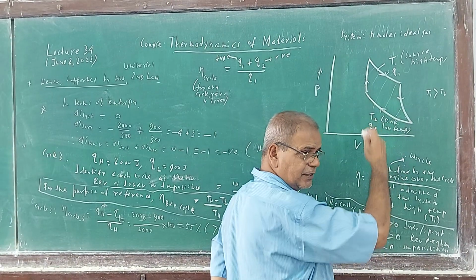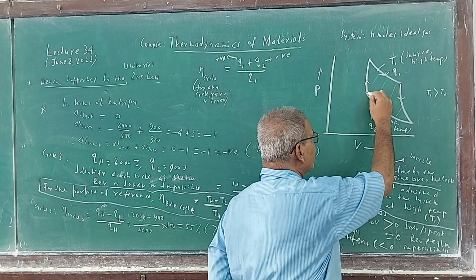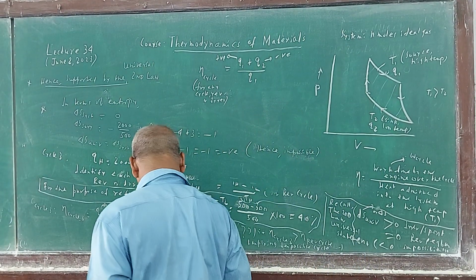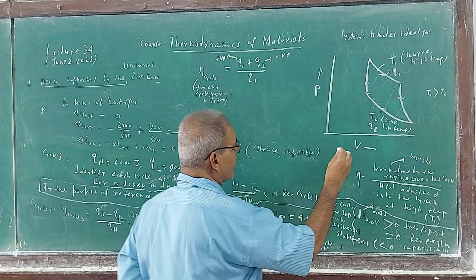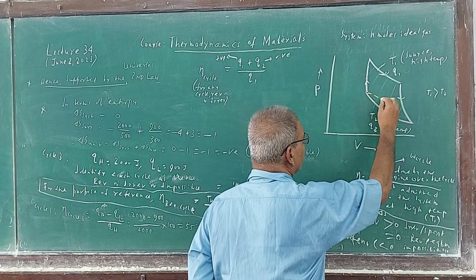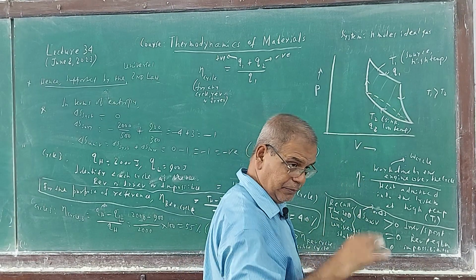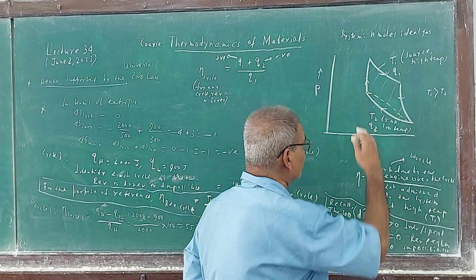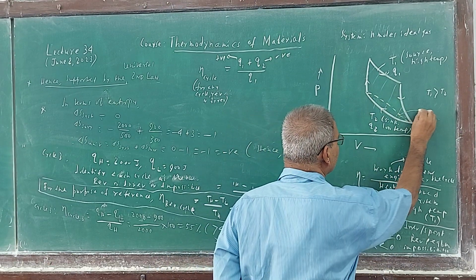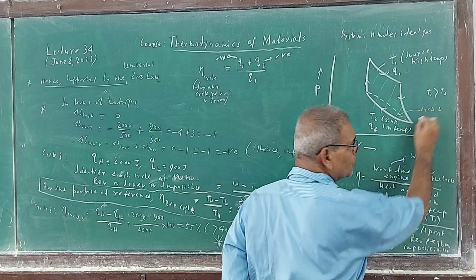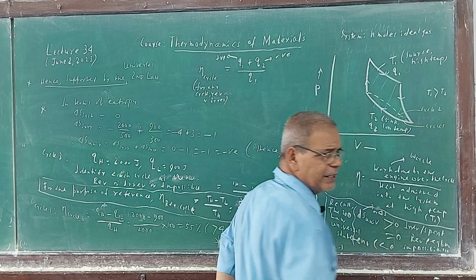Area under the curve is the work done and heat. Same isothermal, so this will be this. I will show you like this somewhere, so that it becomes 1500, the area under the curve, negative though. You can consider the minus is already given. So the absolute value of QL is greater, so the area under the curve is greater. Tell me, which cycle is this? This is for cycle 1, reversible itself.